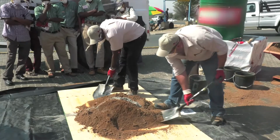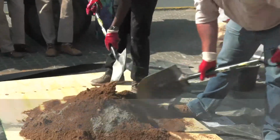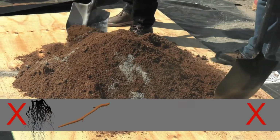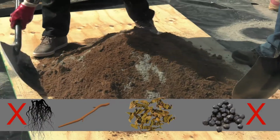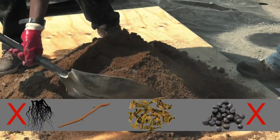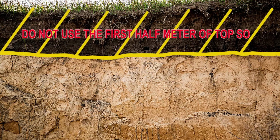River sand would be preferable due to its low clay content. Sand should not contain any foreign objects, for example roots, sticks, leaves or animal dung. This could be prevented by sieving the sand prior to use. Also, it's not advisable to use the first half meter of topsoil when obtaining the sand.